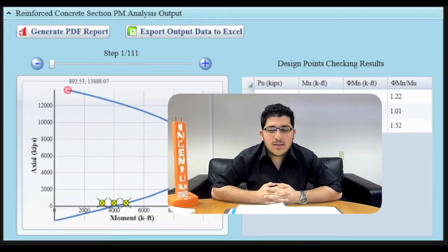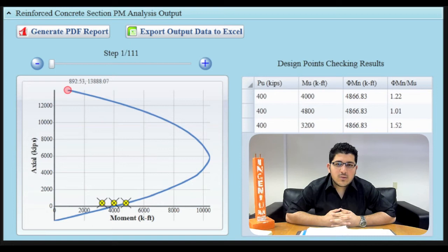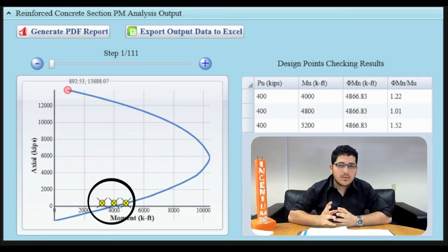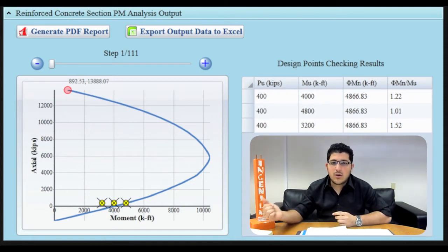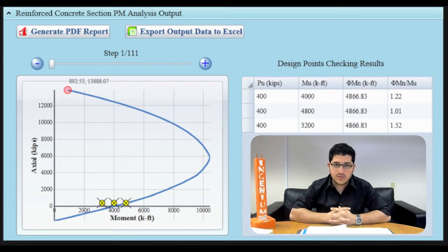To see whether or not the final design of the rectangle with the designated numbers of bars would work to the best of its ability, the PM diagram had to be found. The PM diagram tells us whether or not the column would perform within the required boundaries. There are 3 points on the PM diagram from my right to left. The first one is the lowest boundary, the left one is the higher boundary. The column was supposed to go through the middle of these 2 points.